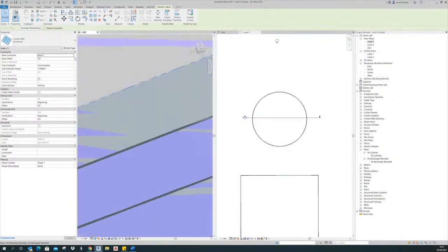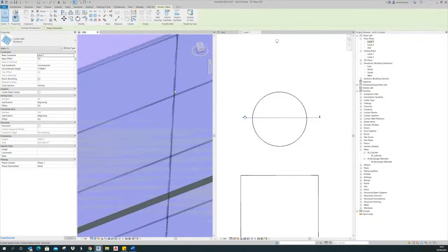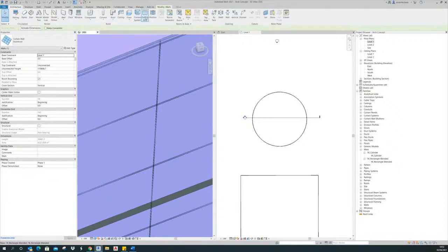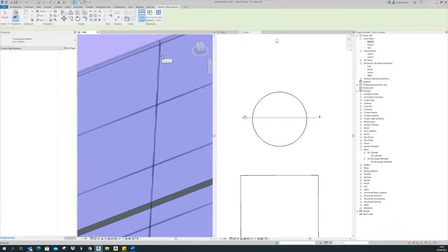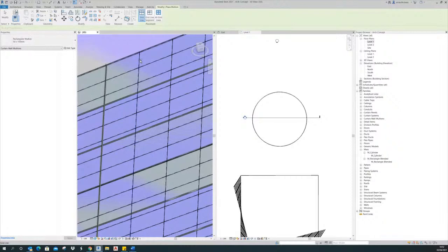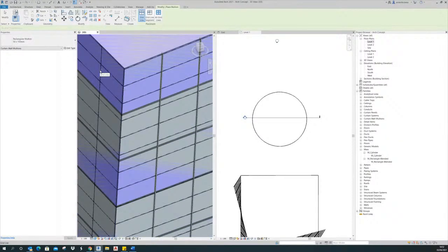element that we did. So when you created a curtain panel, you basically have the cutouts on the curtain wall. You can add mullions into them. So what you do here in the architecture tab, you can add these mullions. Say if you want to add the vertical mullion with this, one by one, you can very well do it. See, if you want to make mullions, say the corners of the building, then that's okay.